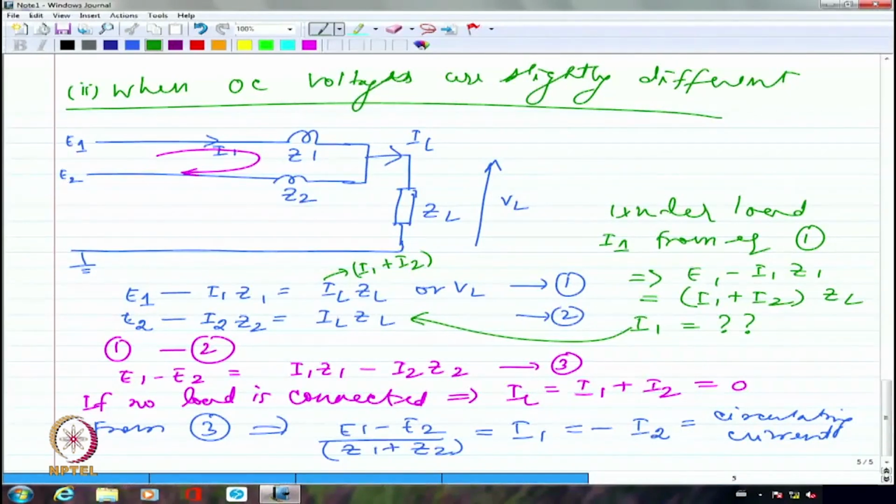Whether I am actually looking at the load division in proportion to their rating, that is what is very, very important. 100 kVA should take the lion's share, 50 kVA should take a lesser amount. And that's what should happen ideally if the impedances are comparable, right?